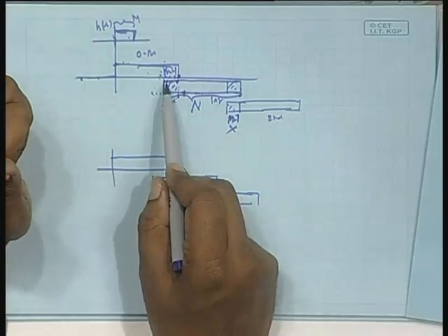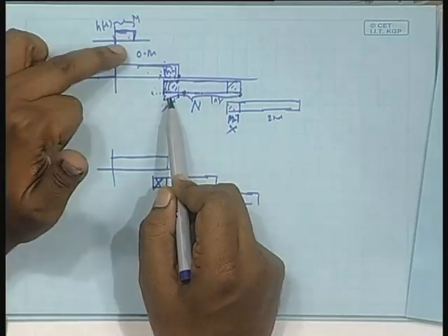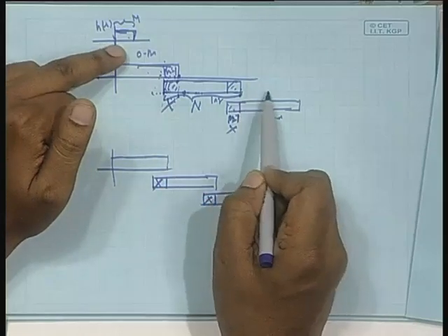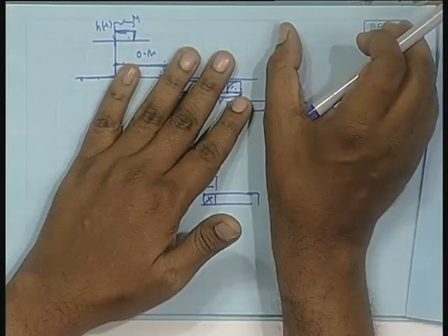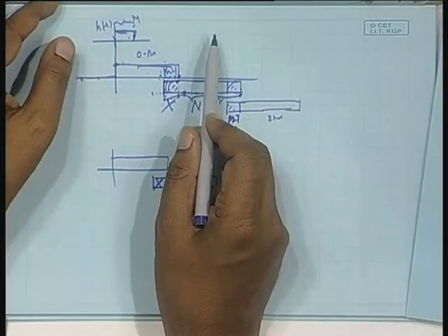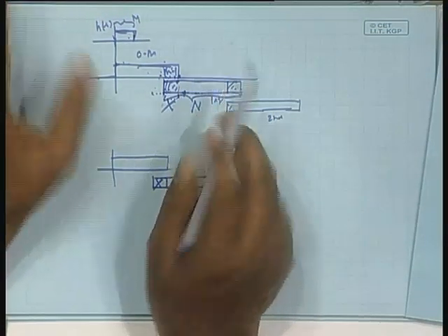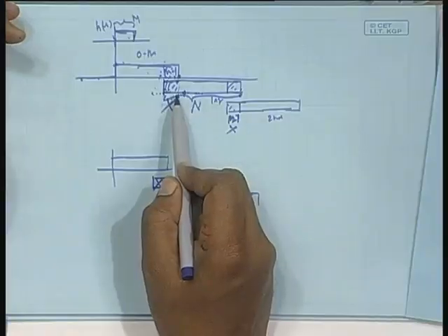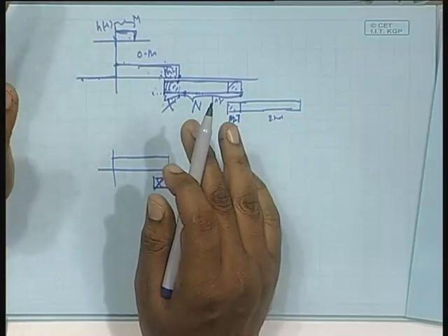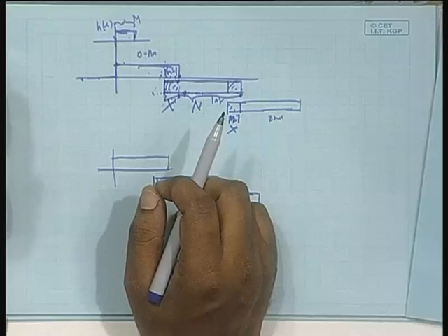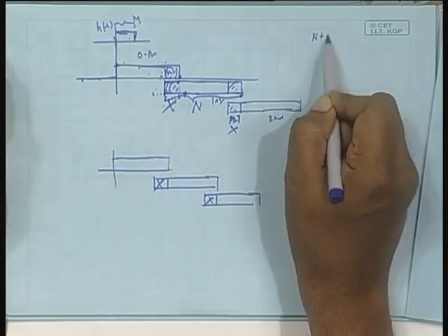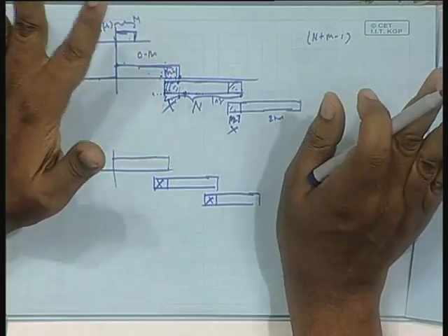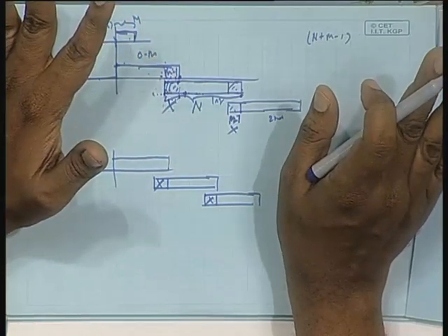So you can tell me, look, fine, you want to do a linear convolution with this block of length capital N and a block of length M. You add M minus 1 zeros to this guy, and N minus 1 zeros to the other. So N plus M minus 1 is the length, fine, that will work. DFT, DFT, IDFT, you get the full output, and there you throw away these samples. I agree, but a DFT of N plus M minus 1 points will have more computation than an N-point DFT. An N-point DFT is much less computation.